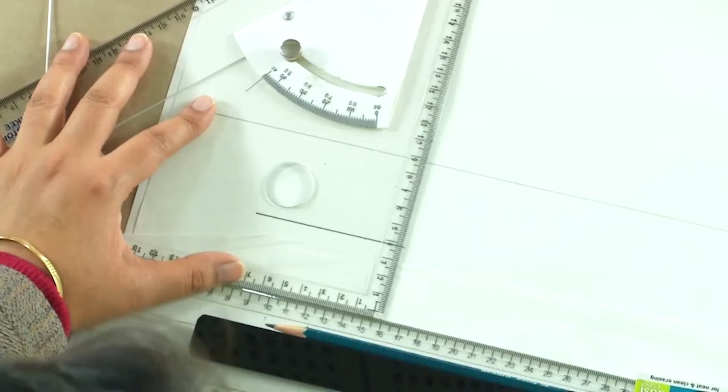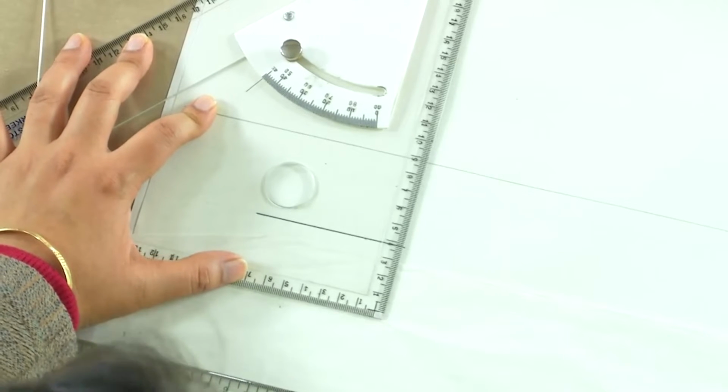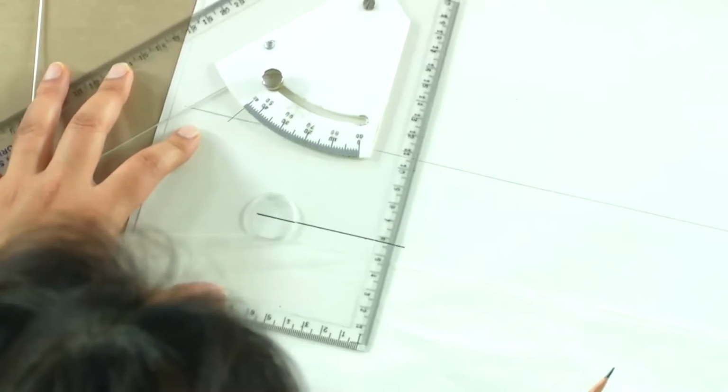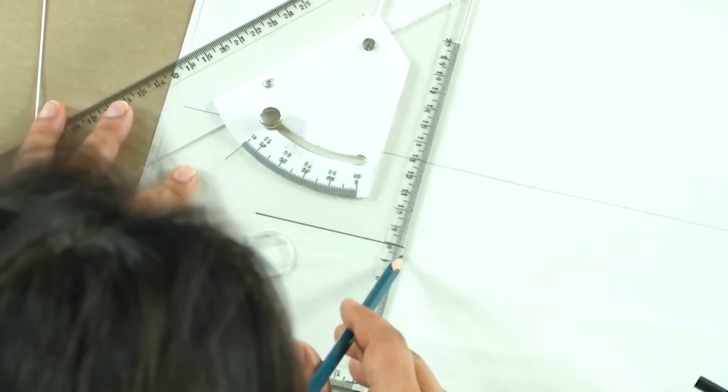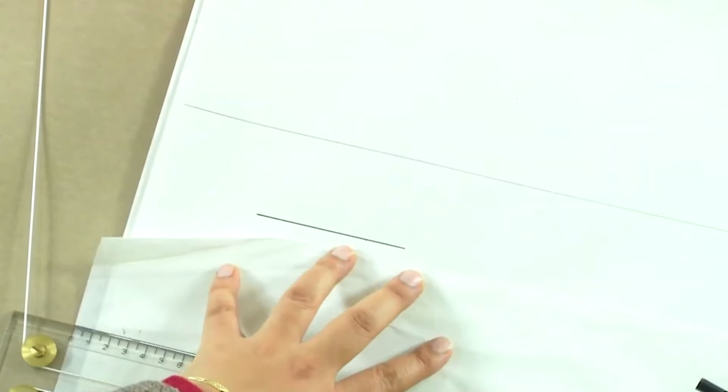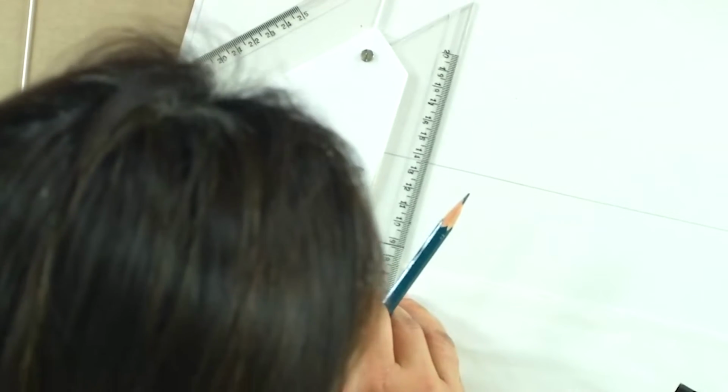Once we have drawn, we could start from the front elevation also or plan also, simply because in our case the line is parallel to both the planes and we will be seeing the true length of the line in both the views. So, we could start from the elevation as well as the plan. I am starting from plan because it is easier at times to draw. Now, this distance is 50 because it was at a distance of 50 mm from VP. Now, it is at a height of 30 mm from HP. So, we will measure 30 mm above HP.